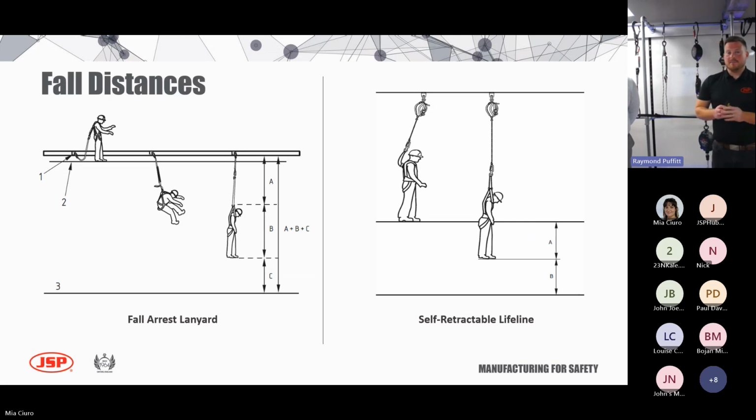We then always think about the heights of the users. So obviously we've got 2 of us here. Obviously Harry's a lot taller than I am, but we always allow for 2 meters per person. And then just a bit of safety, which you can see in the C. C, we always allow for 1 meter of fall clearance beneath us. We want that extra bit of safety, so obviously you're not getting close to the bottom whatsoever. The final figure for fall arrest lanyard is 6.75 meters.